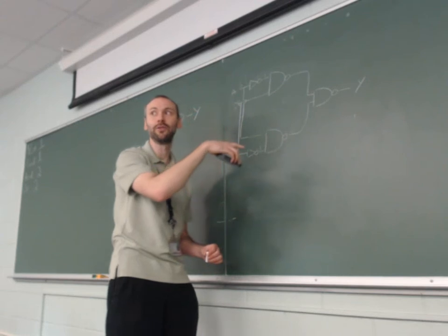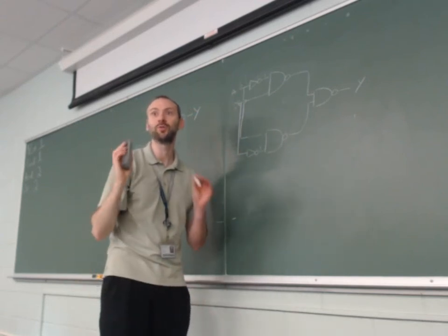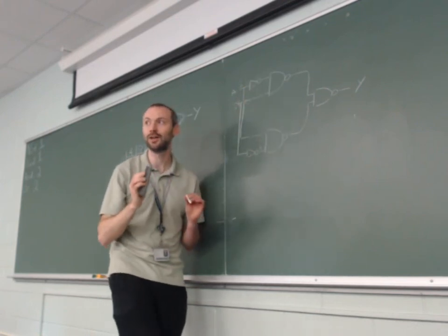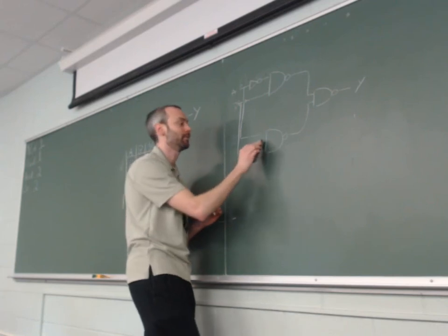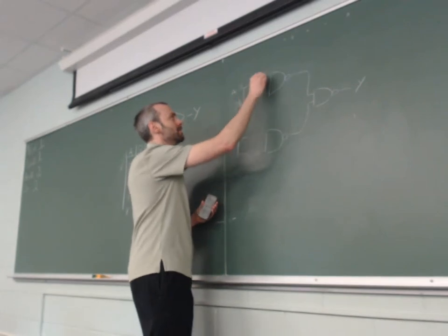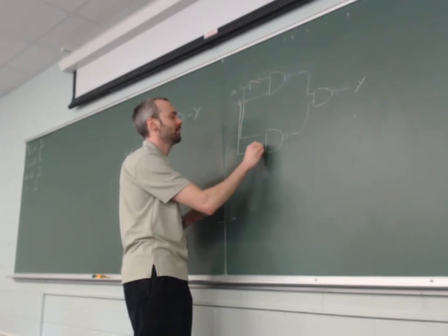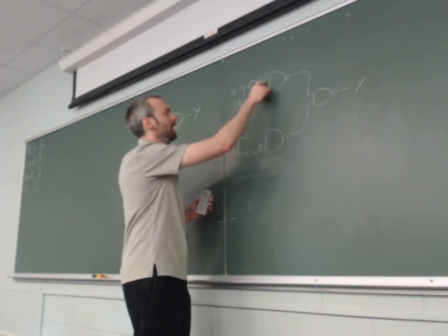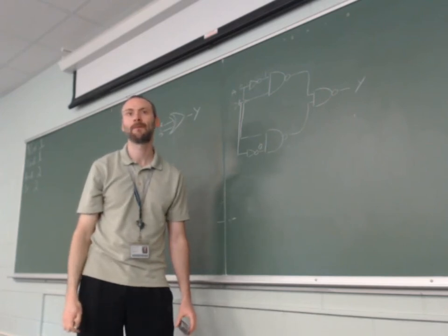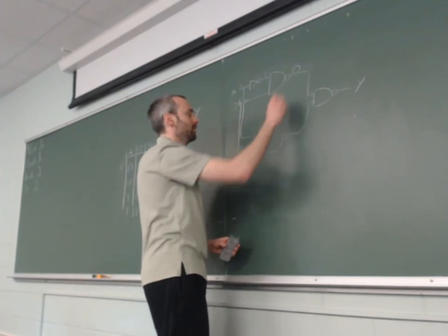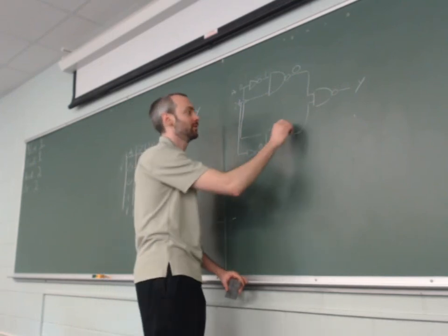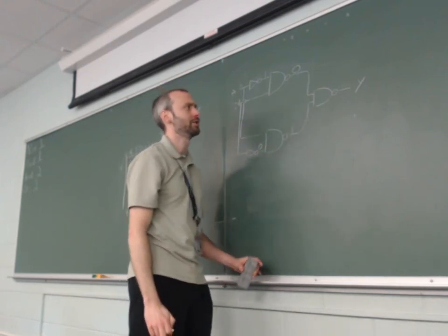By the way, this whole process of writing what the values are on the diagram is going to be really, really helpful, even when we start on our Verilog. You're doing Verilog, you can't figure it out, draw the diagram. Makes them 0, 1, right? All right. Well, that's still 1. The NOT is 0. So what's the NAND of 1 and 1? 0. Okay. What's the NAND of 0 and 0? 1. What is the NAND of 0, 1?